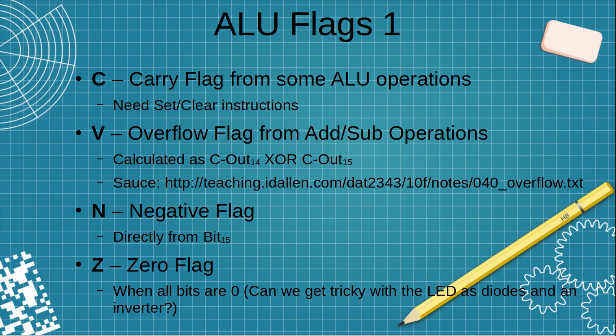Now, what's interesting about the overflow flag is I did find an article online that indicates that the carry out from the 14th bit of an operation exclusively ORed with the carry out of the 15th bit of the operation will indicate whether or not an overflow has happened. So I'm sure you're going to ask, Adam, if you're going to use a full adder, how do you get access to bit 14 for the carry out? I've got some plans for that, so stay tuned there.